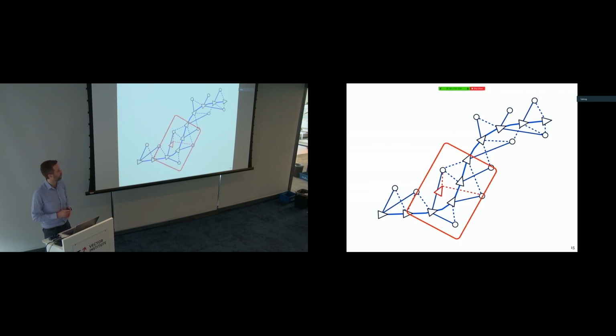And then the nice thing about that is it has the property that if you were to rubber band a section of that map, you don't need to do anything except to just cut out the bits that are not inside your rubber band, and then you can think of the world as just being what's inside this rubber band. And so if we're trying to repeat the path now, and we have a new pose, all we have to do is re-observe some of the landmarks that are in our map, and then we can determine the transform between the live pose and the pose that's in the map.